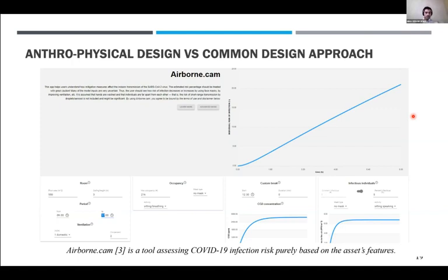How big is the room? What is the ventilation rate? What are people doing? So we have the ventilation rate here. We have the period of time that they're spending, the office hours between 9 a.m. to 5 p.m. We have the room size. These are exactly taken from the case study. And the occupancy, how many people are staying there, they're wearing no mask, and what they're doing, they're sitting, so the activity type. So there are many aspects of our simulation involved in here.